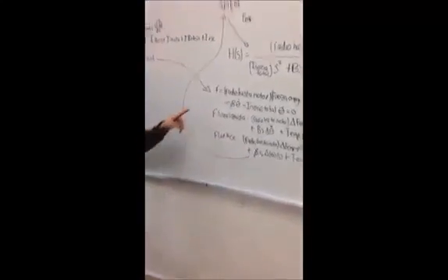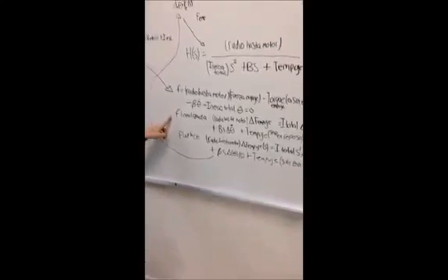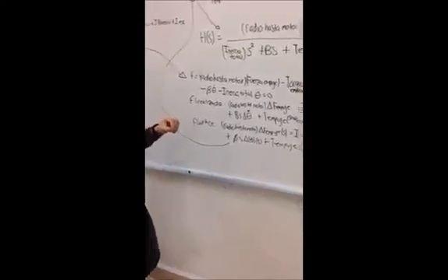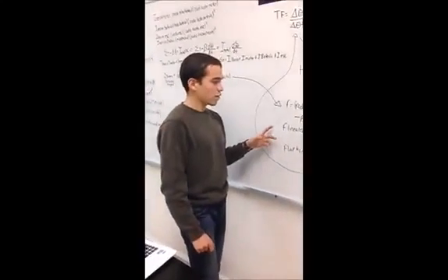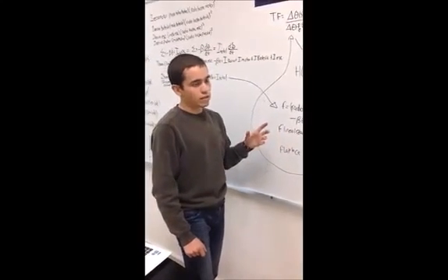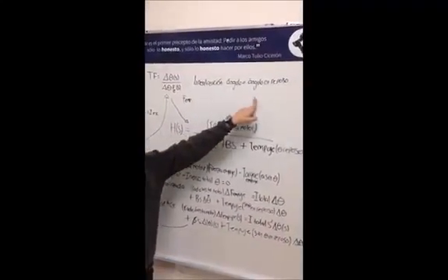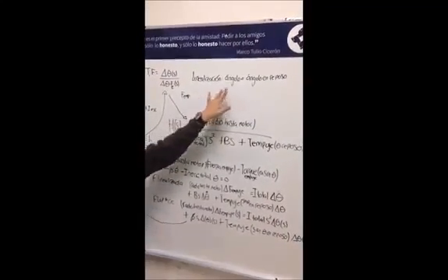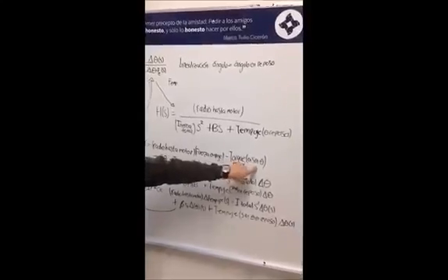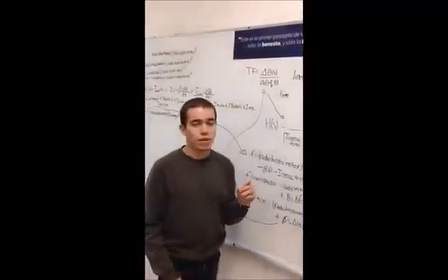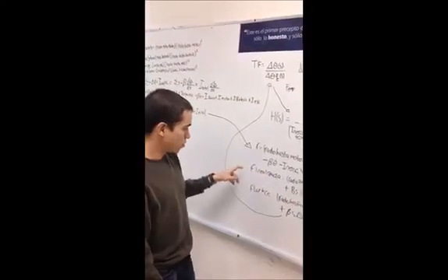Then we will need to linearize this function because it is not linear. And we obtain that with the Taylor series. With the linearization, the only thing that we get is that the angle theta that we have in here is the rest angle that I mentioned before, that is 25 degrees.